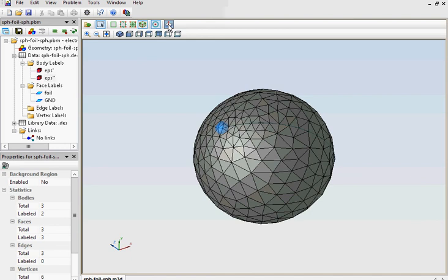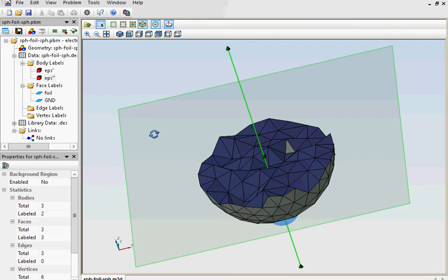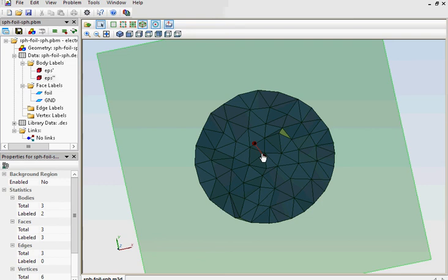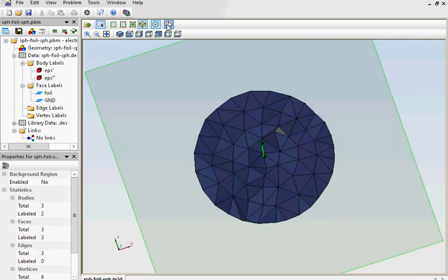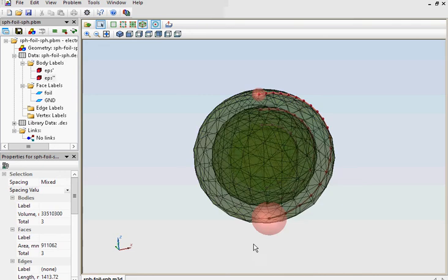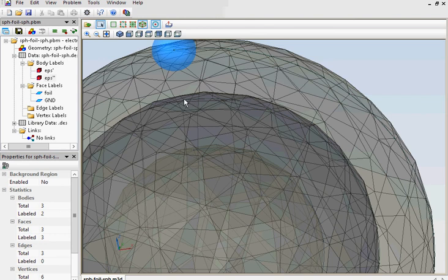But if you look inside, you will see that the mesh elements are still there. That's because we haven't assigned spacing for the inner spheres. Inner spheres have automatic mesh spacing, and QuickField decides that such elements are good enough to build the mesh in the internal objects. Well, you can select the vertices of the inner objects and adjust the mesh spacing there individually.